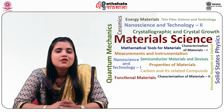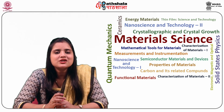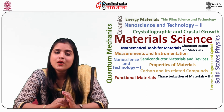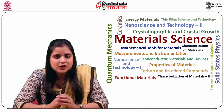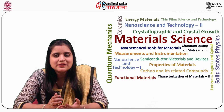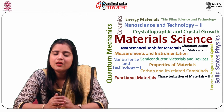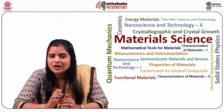We will now discuss the various configurations for CV measurements. Capacitance voltage measurements or CV measurements can be done in the following two different configurations. First one is the quasi-static configuration. This configuration corresponds to the equilibrium condition. The CV measurements in this configuration are made by sweeping bias voltage applied across the sample. The displacement current is measured as a function of time.